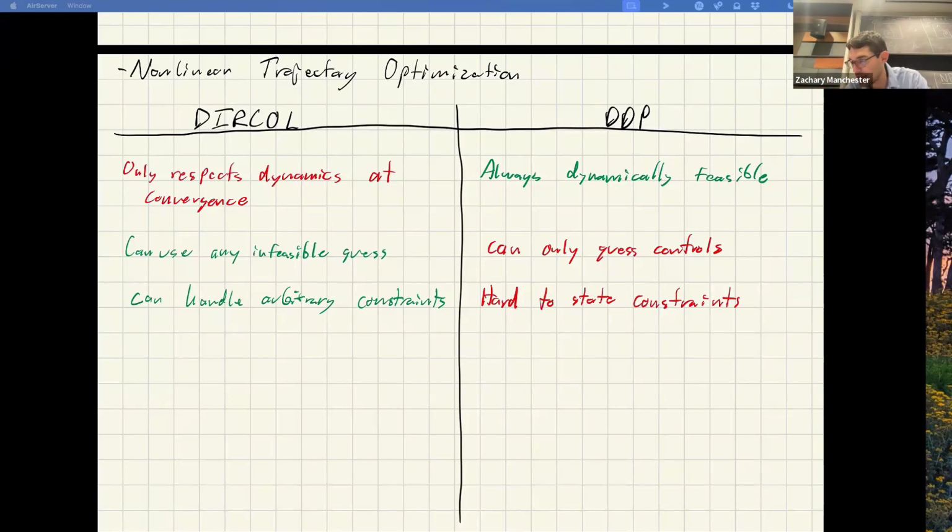In fact, that is quite useful in applications because a lot of times, if we're doing this online, we can't solve the nonlinear Trajopt problem fast enough. So what we'll do is approximately solve it with DDP, take a couple iterations, and then in between those solves, we'll track that with the LQR tracking gains that come out of this thing. And that lets us run a much, much higher rate, low-level feedback controller. Say I can only solve the DDP problem at 10 hertz, I could run that K matrix with 500 hertz low-level feedback in between those solves, and that can help a lot. So that's nice.